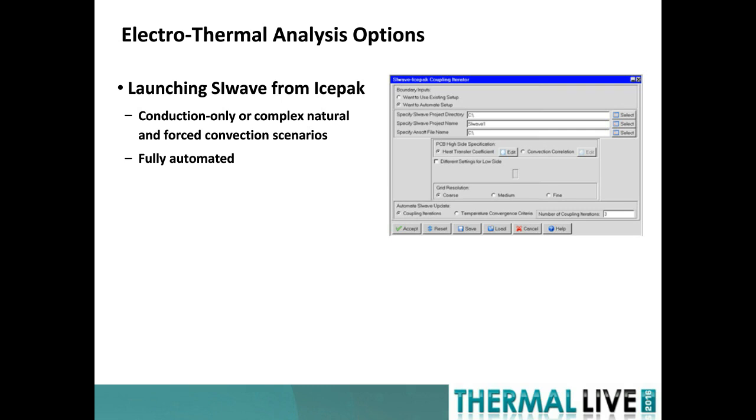So, for example, when you're mapping temperature from IcePak to Mechanical, the temperature map is on a CFD mesh, and it's being mapped to the mesh in Mechanical. So the meshes are different. So there's interpolation that takes place to accurately map temperature from one mesh, a CFD mesh, onto another mesh, a Mechanical mesh. Okay. So there's some interpolation that's used.